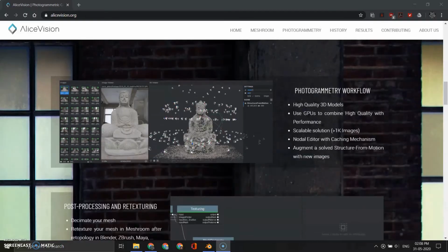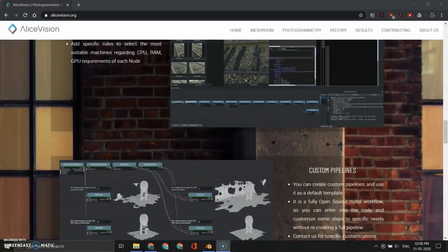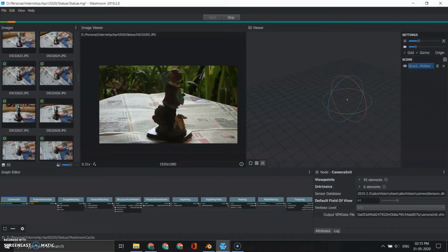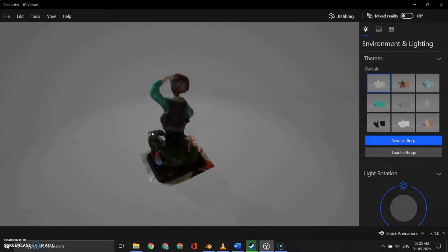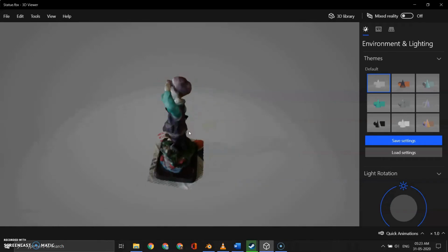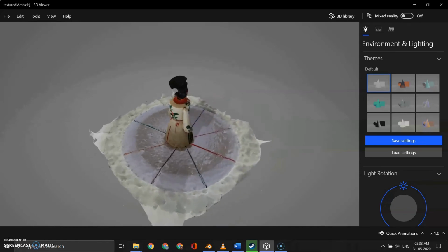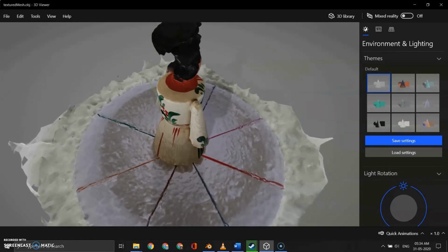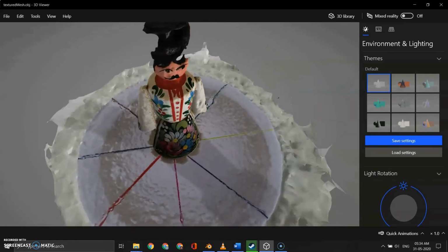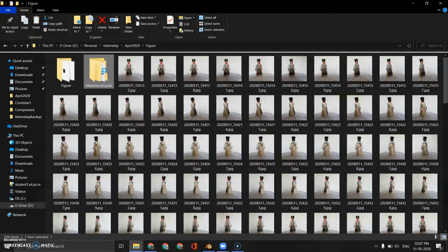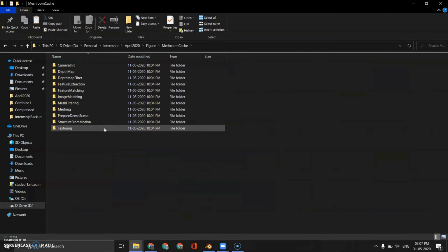Meshroom is a free open source software based on the AliceVision photogrammetry framework. It has a relatively simple and straightforward UI, and in my opinion, is the best among the free photogrammetry softwares available. However, the software is very aggressive in removing shadows and is not very good at handling reflections, making it unable to detect black objects or render black parts on objects. Moreover, every render fills up several GBs of disk space, with intermediate renders that need to be deleted manually after the final render is obtained.